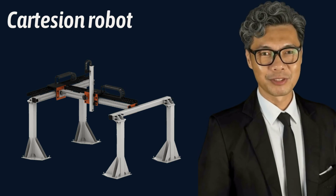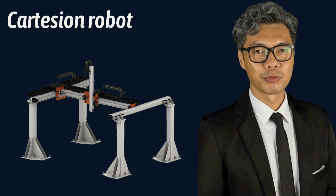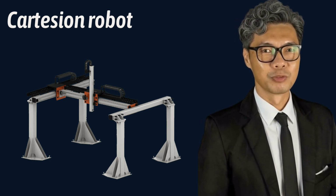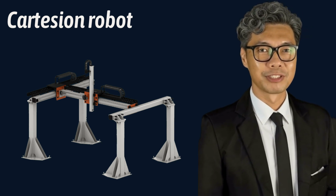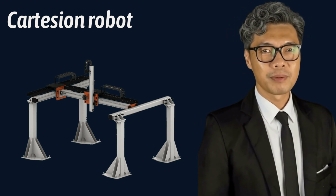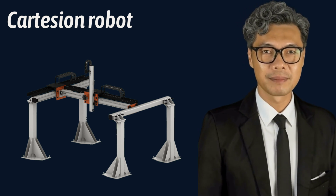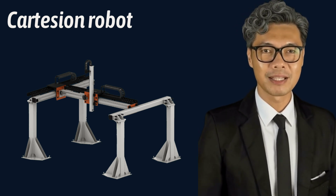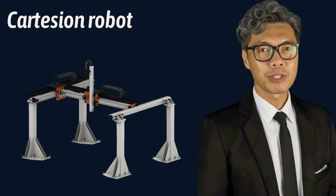The fourth type is the Cartesian robot. It moves along 3 straight axes: X, Y, and Z. Select a Cartesian robot for simple, straightforward processes that require the robot to travel across a large working area. A common application I see regularly is picking parts directly from plastic injection molding machines.